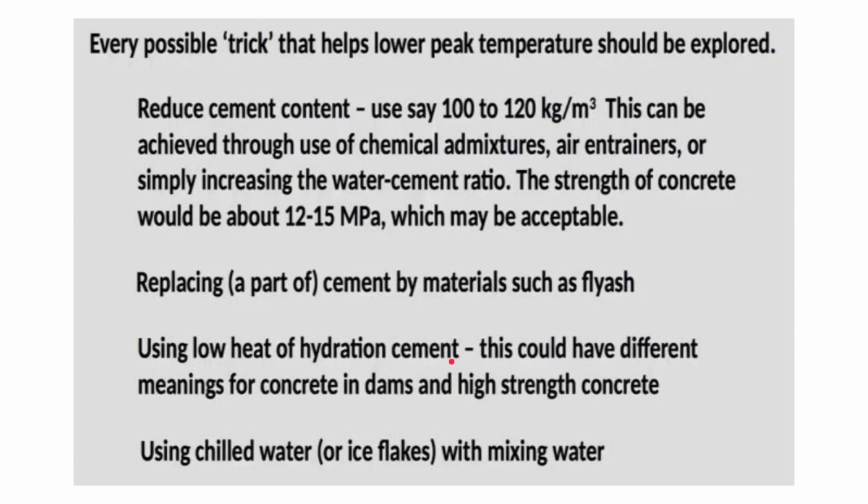Using low heat of hydration cement. This could have different meanings for concrete in dams and high strength concrete. Characteristics will be changing due to environmental conditions and various other factors. So using chilled water or ice flakes with mixing water can also be a good alternative.